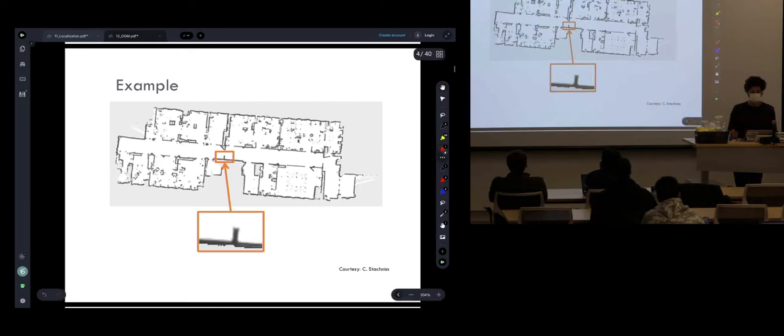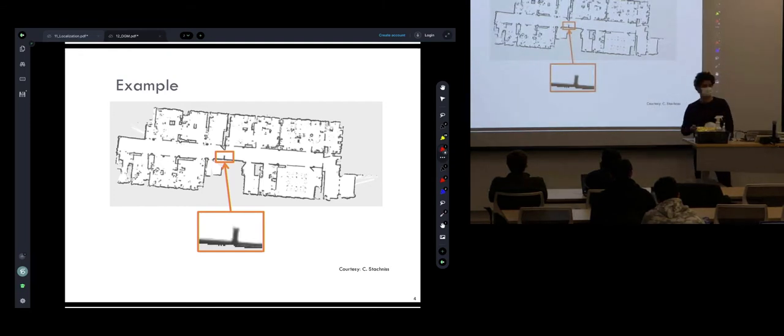Here is an example of an occupancy grid map. This is a building on the Freiburg campus in Germany. Again, the data set is open source and is available. You see, when you build the map, the color map is usually grayscale from 0 to 1. So the darker cells mean occupied, and brighter means free. When it's gray, it's in between, a range that we don't know, it's unknown. Now you can flip the color map, or you can choose different color maps, but this is very standard in papers and literature.